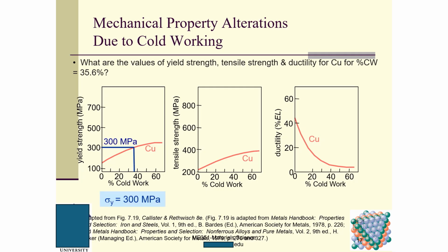For this percentage, the yield strength is 300 megapascal. For the same percentage, we can read the tensile strength. Also for the same percentage, the ductility equals 7%.